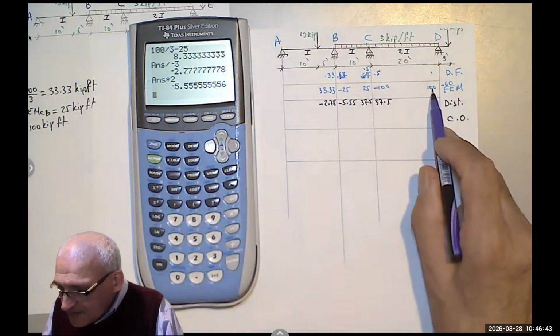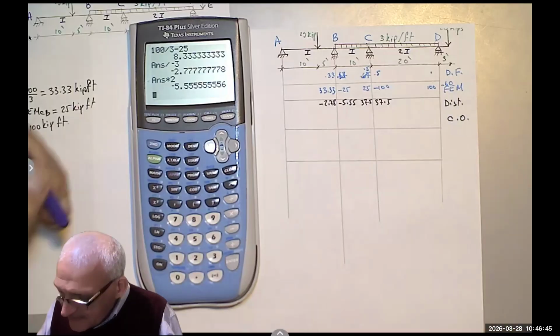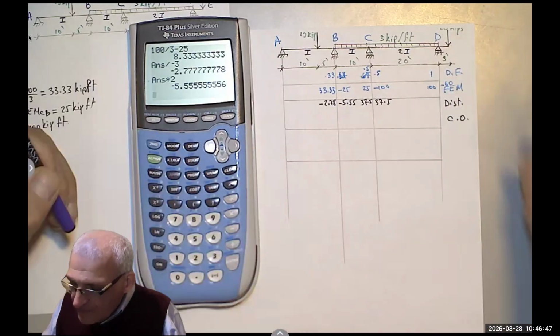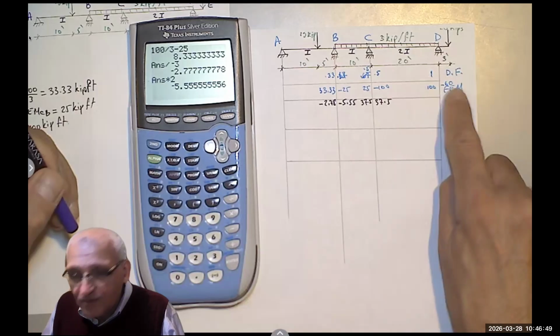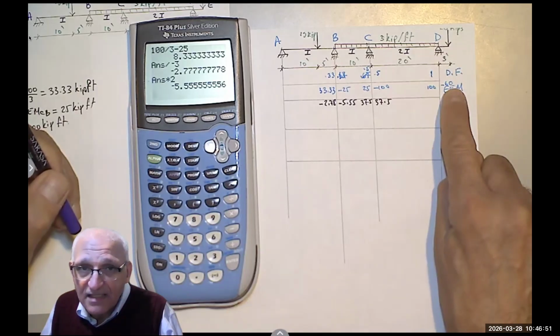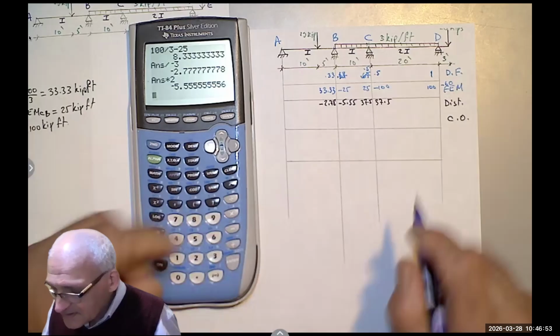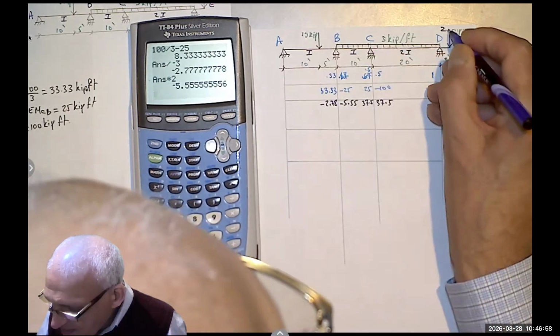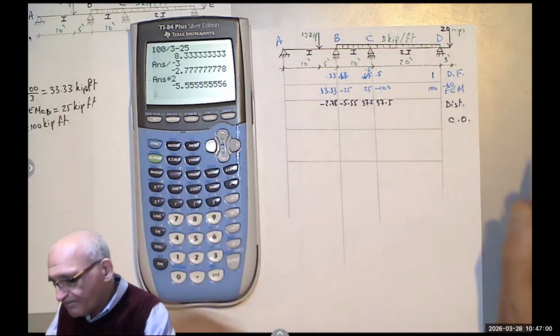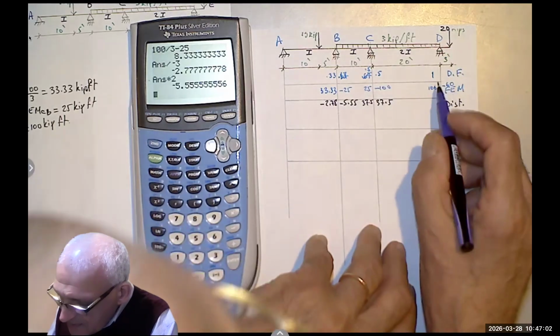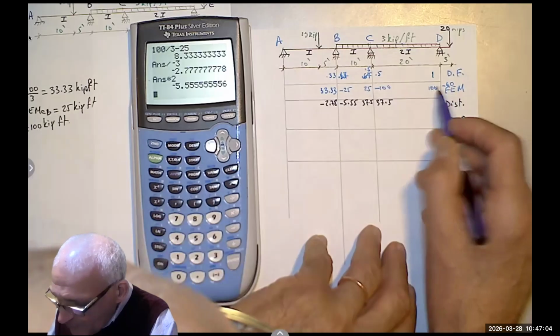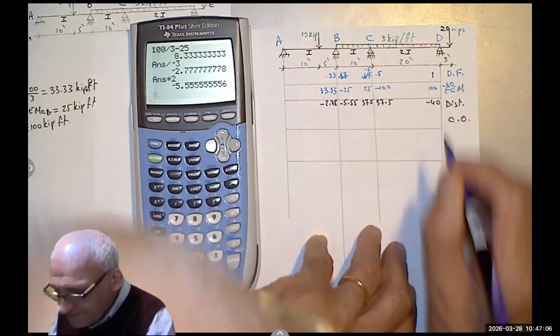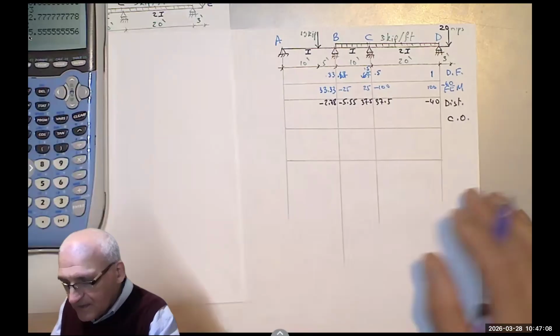Here it's 100 and negative 60. Notice that all of it will go to the fixed part. The moment here would always remain negative 60, no matter what happens, right? Because calculating from the right, this is 20 times 3 is 60. So the difference is 40, so you get negative 40. And we are done with the distribution.